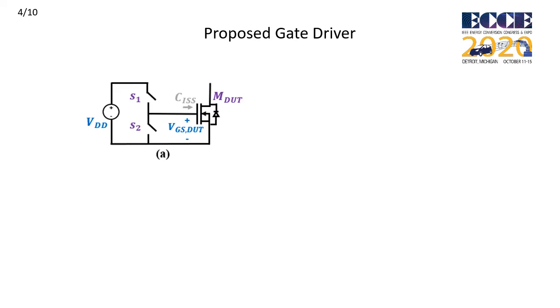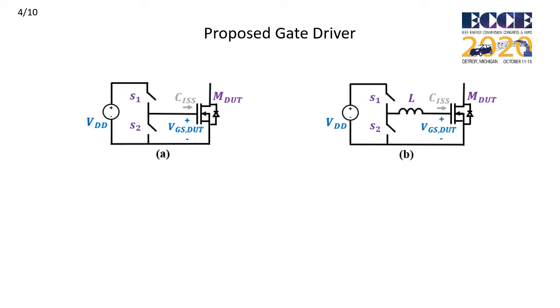So here we've got unmitigated CV²F loss, whereby we lose half of our energy in charging up the input capacitance, and we dump out the remainder into ground once we're done with it. And we do this every single period. So to start changing this into a resonant gate driver in which most of this energy is instead recovered or conserved, we can start by adding an inductor in series with the gate.